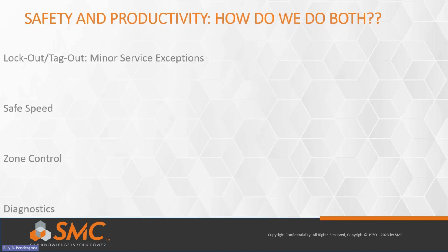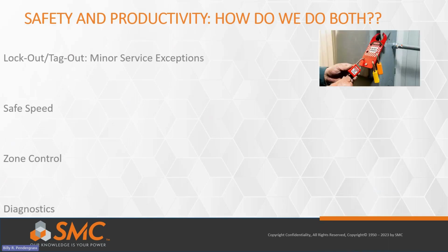So how do you realize these savings? Lockout tagout would be the first. These activities typically exhibit all or most of the following characteristics: short in duration, minor in nature, occur frequently, performed by operators or maintenance personnel, require minimal disassembly, represent predetermined cyclical activities, minimal interruption to production, occur even at optimal operating levels, and require task-specific personnel training.